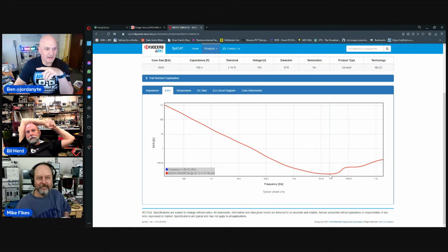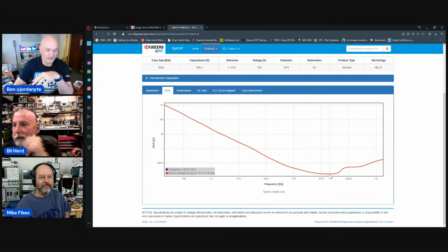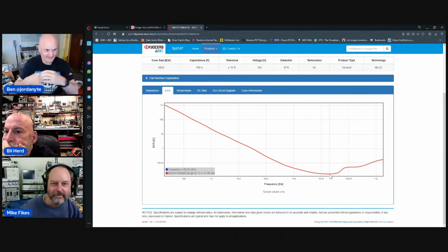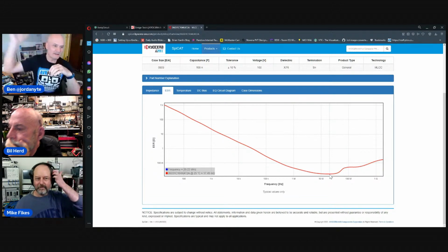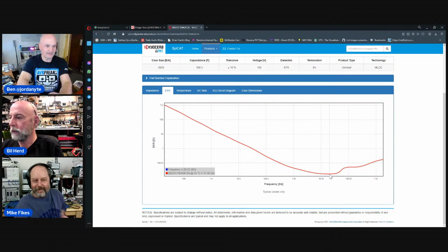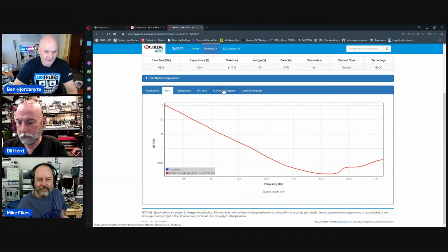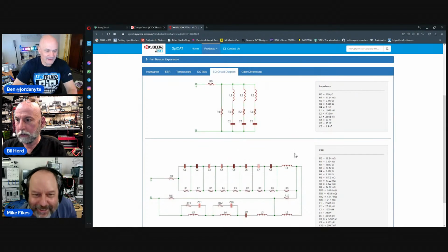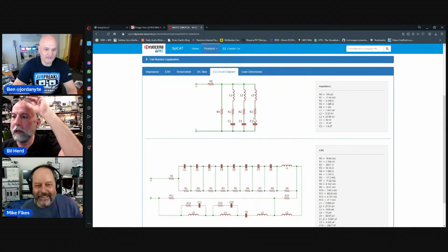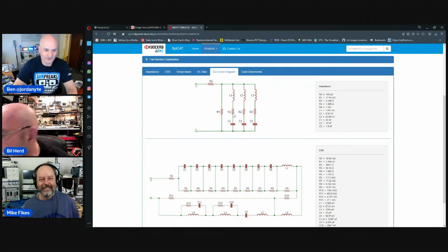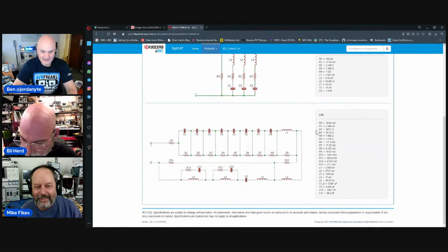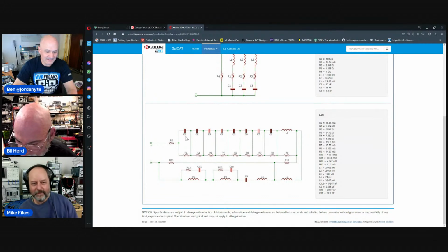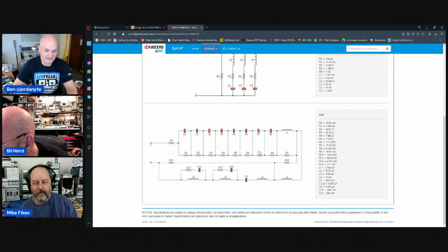And yet we're talking about these being bulk storage across your board for a chip that's pulling switching transients that have harmonics well up over a gigahertz often, right? So here's the equivalent circuit diagram. Oh, wow. That's pretty complicated. That looks like screenshots from Eagle, I'm sure. But look at this. If you download the SPICE model from Kyocera, this is what's in it.